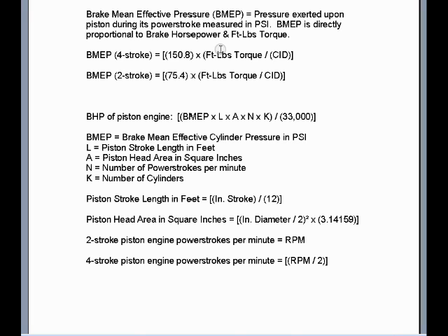In this case, we are using a 4-stroke gasoline piston engine. 4-stroke duty cycle reciprocating piston engines include downstroke on the air intake cycle. In the case of gasoline, it would be both air and fuel intake, then compression on the upstroke, power on the downstroke, exhaust on the upstroke. That would represent the 4-stroke duty cycle. In this case, we're using a 4-stroke, 6-cylinder, gasoline-powered automobile piston engine.